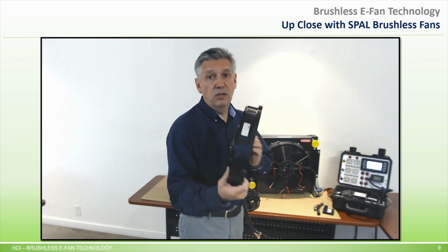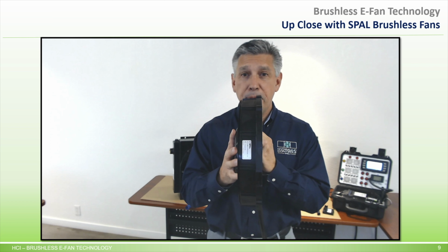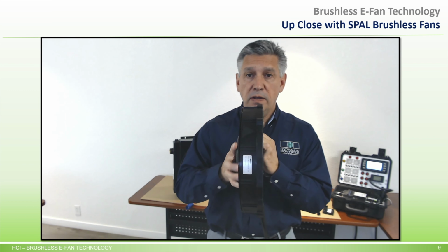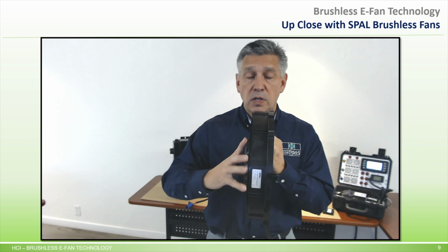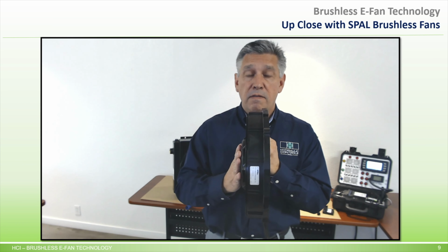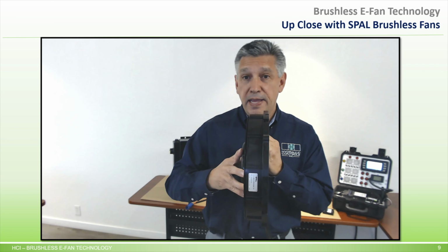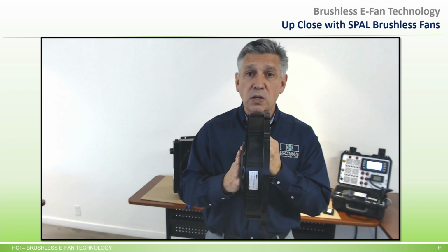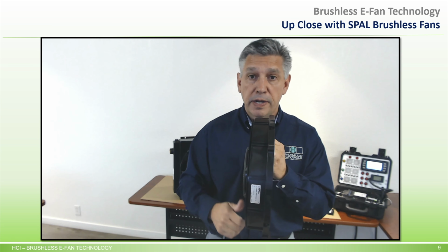So next, let's take a look at this 12-inch fan. This is a high power motor one. It's a 4100 RPM fan, and at max it has 12 volts. At maximum speed, you're looking at probably an amp draw between 40 and 45 amps. But it's also going to produce up to 2200 CFM. So a lot more airflow.